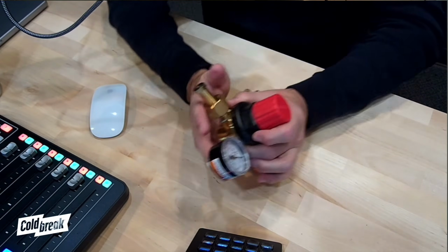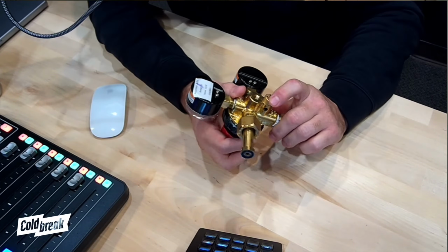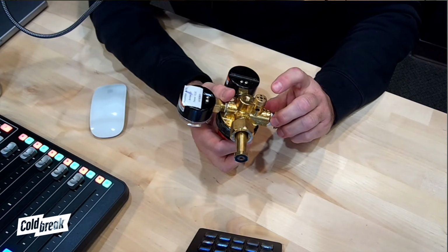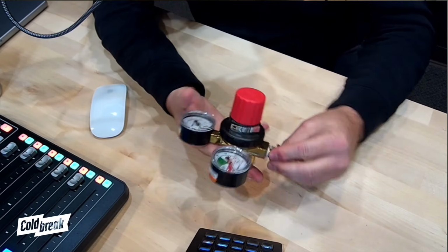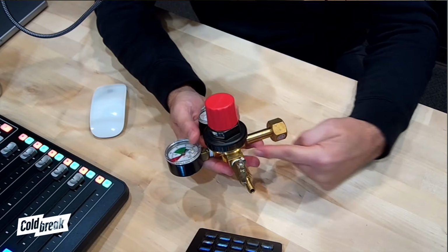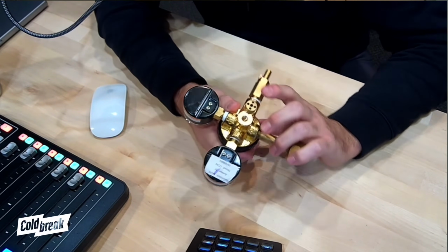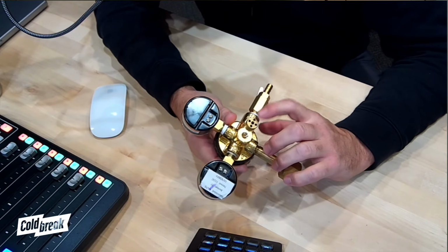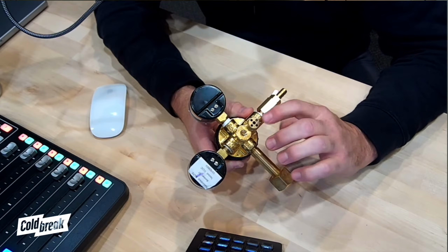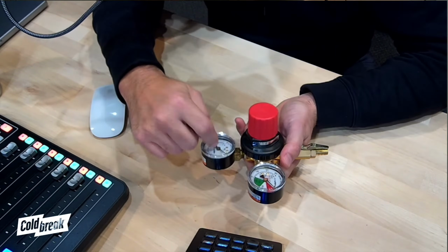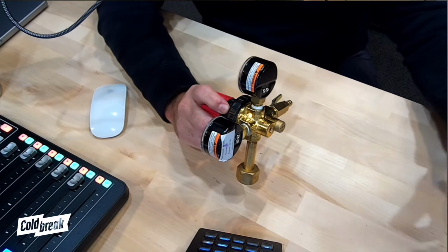One of the things you'll notice on the back of some regulators is either a PRV valve like this, or, depending on the manufacturer, it will come out the corner as another valve that you can pull that will also relieve some pressure. This is a safety valve that will pop, typically at about 52, 53 PSI. If you go too high on the gauges here, this will just open and all your gas will start escaping out the back.